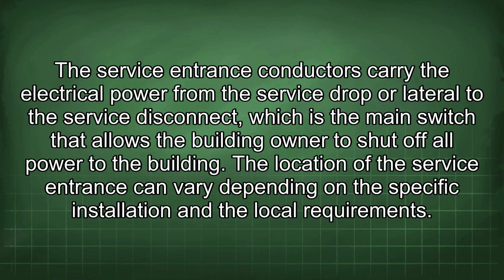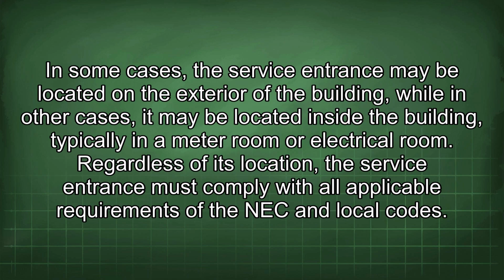The location of the service entrance can vary depending on the specific installation and the local requirements. In some cases, the service entrance may be located on the exterior of the building, while in other cases, it may be located inside the building, typically in a meter room or electrical room. Regardless of its location, the service entrance must comply with all applicable requirements of the NEC and local codes.